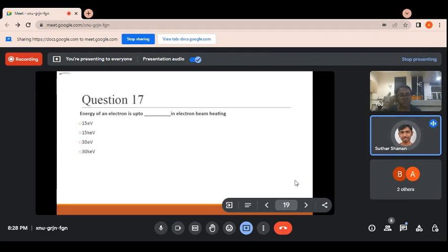So then what is the main difference between positive and negative photoresist? Basically, with positive and negative photoresist, the UV exposure removes different regions. For example, when we want to create an island, we go for negative photoresist.